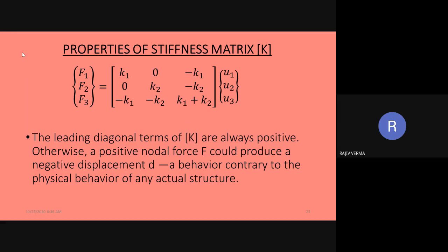It simply moves from one point to another point, but the body is in fact intact. So obviously, a body is going to undergo deformation only when it is constrained at some locations. Therefore, to solve these singular matrices, we are going to impose some boundary conditions before it is solved.